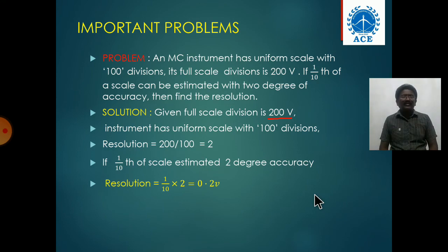Actually this circuit has one PMMC meter, one battery, one resistance, and the unknown resistance across the terminals under different conditions. So you can calculate the value of the resistances and unknown resistances. Here unknown means the intermediate values. So this is the idea about the ohm meter.